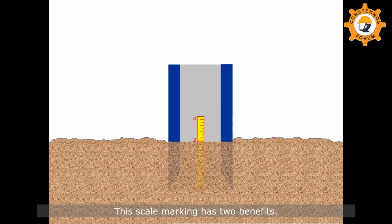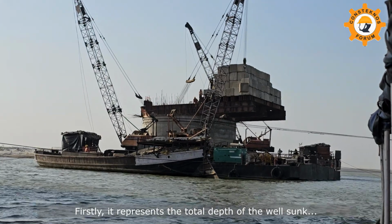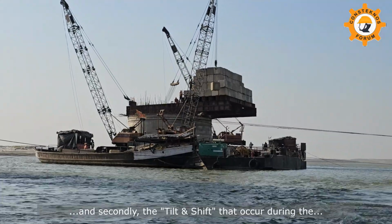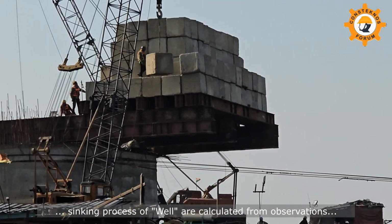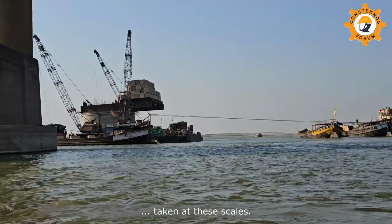This scale marking has 2 benefits. Firstly, it represents the total depth of the well sunk, and secondly, the tilt and shift that occur during the sinking process of well are calculated from observations taken on these scales.